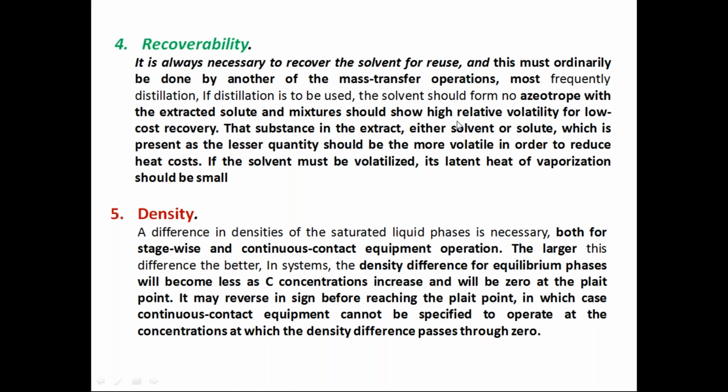The substance in the extract, either solvent or solute, which is present in the lesser quantity, should be the more volatile in order to reduce the heat costs. If the solvent must be volatilized, its latent heat of vaporization should be small.